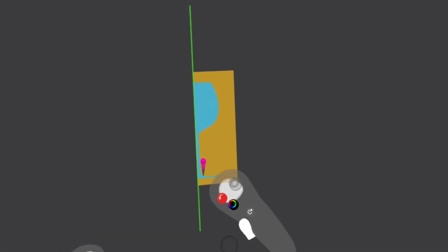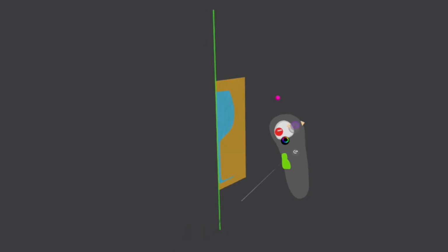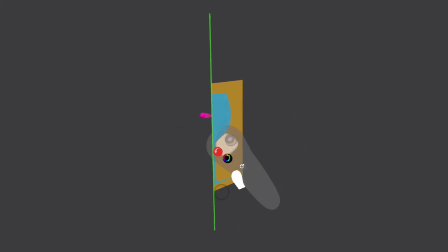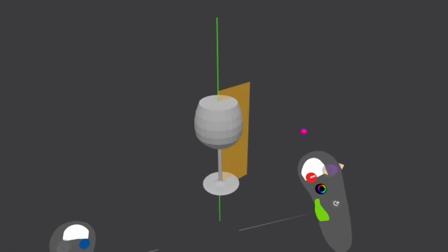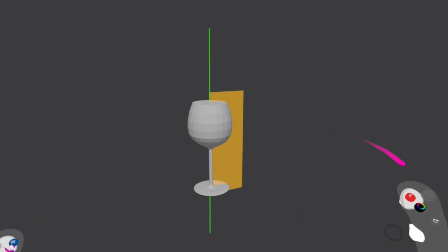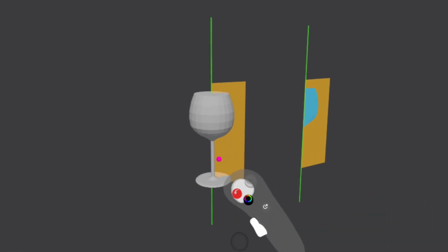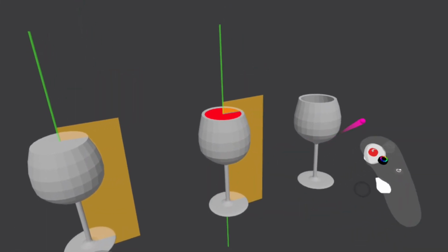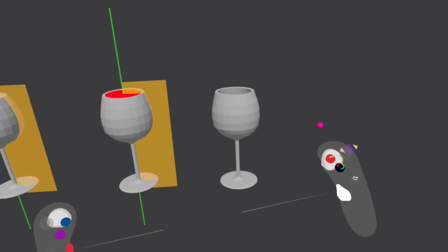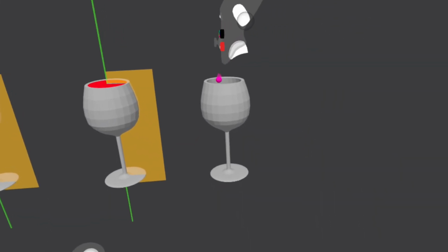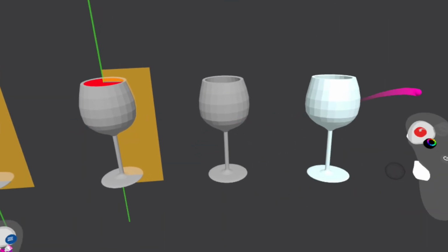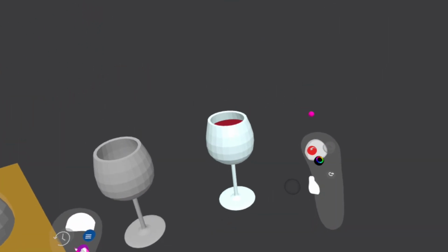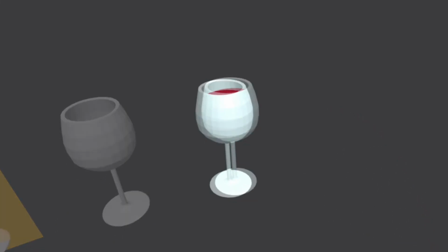So now we're going to show a little bit more of a complex revolve, and we're going to be making a wine glass. So first, a closed 2D sketch is created in blue and revolved around the centerline axis. That closed sketch just means it will make a complete solid. But we all know a wine glass needs to be hollowed out, so we're going to be using a second revolve to actually subtract from the middle. So now a second sketch is made, and when that second sketch is revolved, it cuts away and hollows out that form. Then finally, the material is changed to glass and the form comes to life as a wine glass.